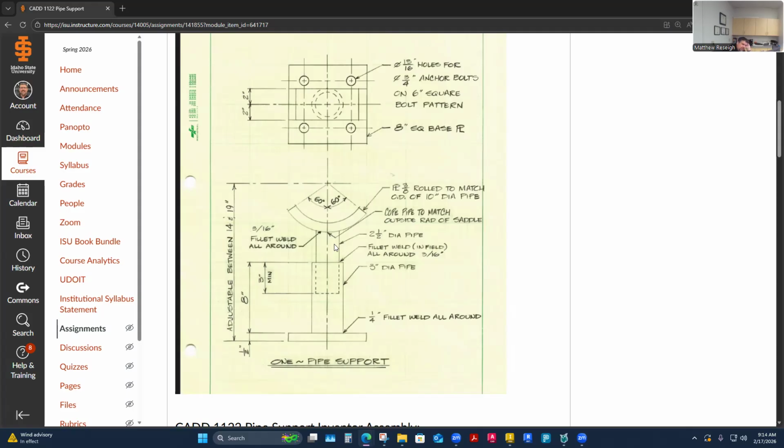What I do need is a relationship where I need these two to slip together. I feel like my engineer's done a little bit of work because he's given me some specific pipe sizes, so maybe they've already kind of figured that out. But what I'll have to really be careful of is that the OD of this one slips into the ID of this one. So my pipe selection for the 2.5 inch OD, like what schedule it is, doesn't really matter, because I know that the 2.5 inch pipe, no matter how thick it is, is going to have a real consistent OD. According to those charts, you notice that the ODs were always consistent. The IDs change based on schedule.